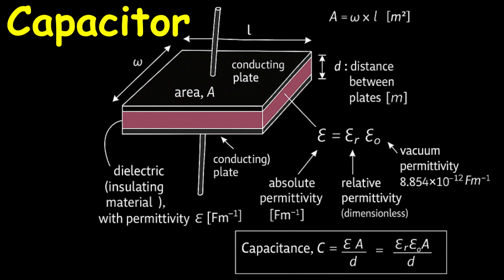So there you have it. The parallel plate capacitor, which at first glance might seem complex, is really just a story of three simple ideas. It's a sandwich of two conductive plates, whose ability to store energy is maximized by making them as large as possible, placing them as close as possible without touching, and filling the gap between them with a special insulating material that enhances the electric field. Area, distance, material. Those are the secrets.